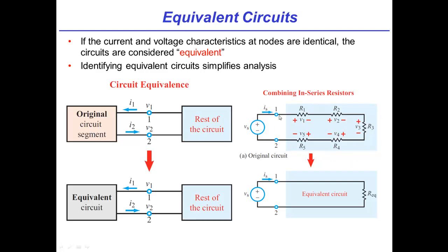All right, so the question is, Michel, what's the voltage across the 5 resistors in series? So it's going to be V1 plus V2 plus V3 plus V4 plus V5. Right. And I went clockwise. What is that value? It turns out that's going to be the value of Vs. Aha, right? So we have Vs across those 5 resistors in total. Got it. Vs, that makes sense.